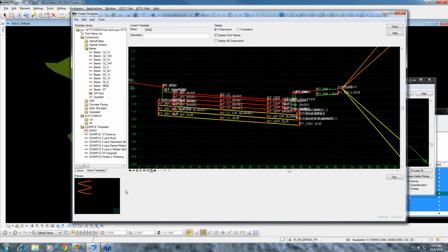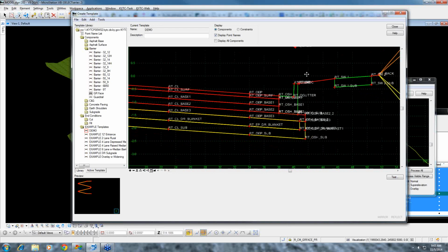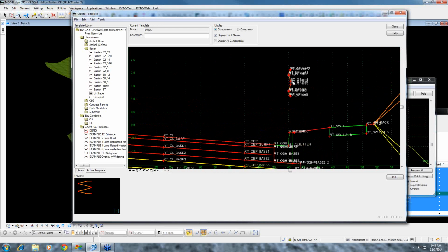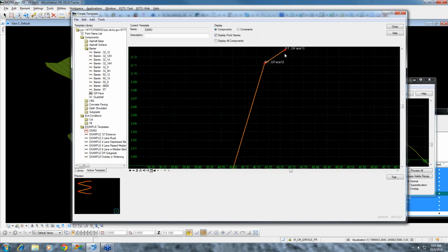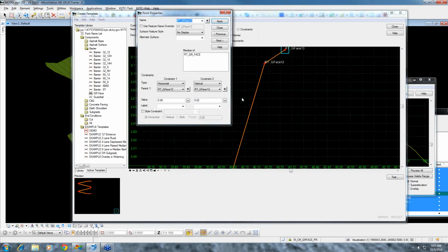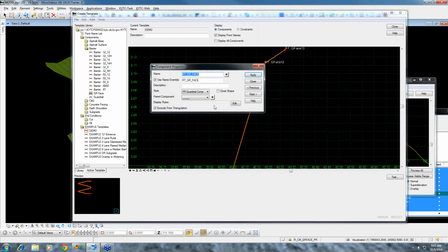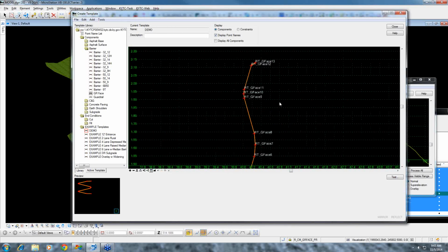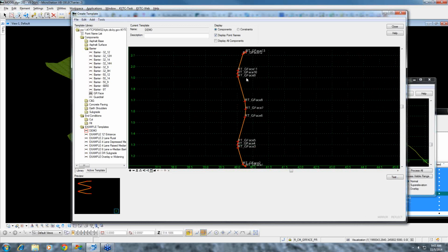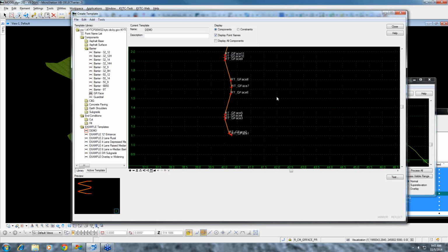So we zoom back in there, and we grab that point, zoom in, place it. So now we've got that face. It's right above there. And these points, we set this not to triangulate. No display on the points, and exclude from triangulation. That way it keeps your model from being all screwed up. This is just for pretty stuff.